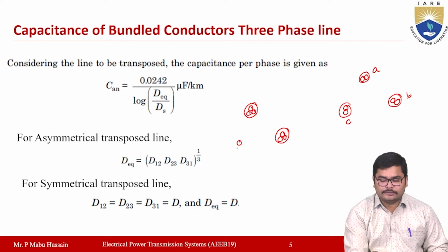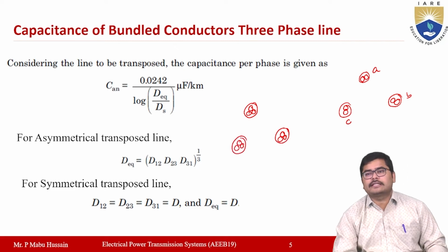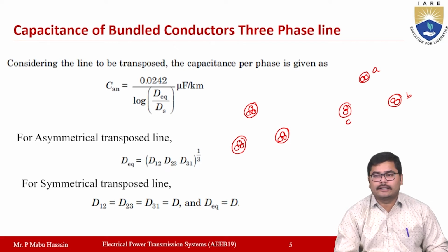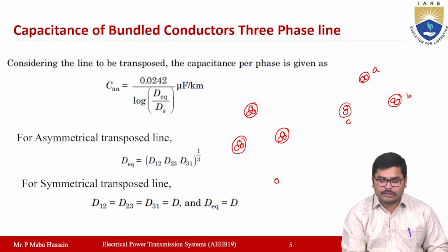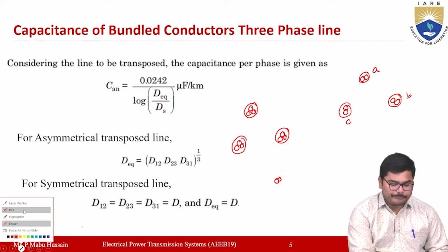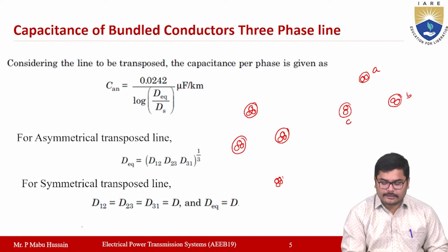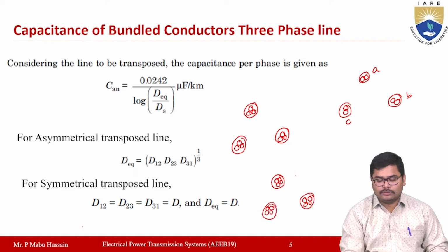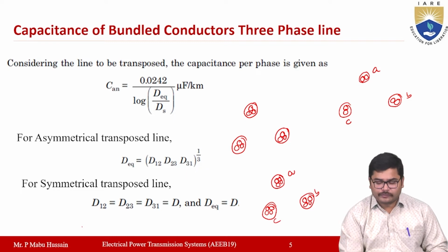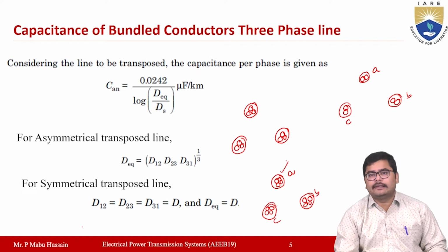So like this. So now this configuration is called the 3 conductor configuration of bundled conductors. Sometimes you may be even having the 4 conductors also. So the 4 conductors, those will be represented like this, like a square. So now A phase, B phase, and C phase. Each phase will be having the 4 subconductors, right? Now this each phase you can call it as a bundled conductor.